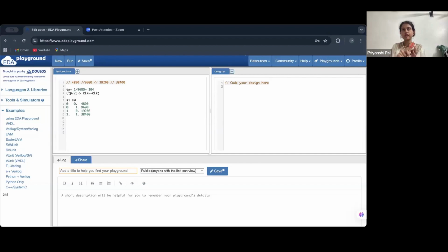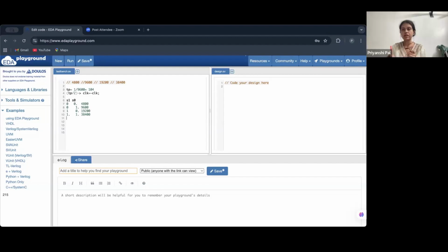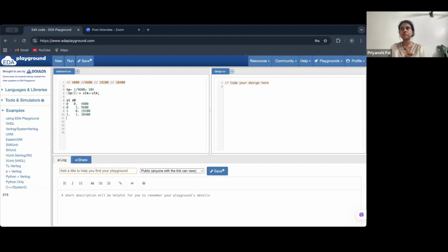The line for data transmission from master to slave is known as MOSI, and for data transmission from slave to master is known as MISO. So what is the role of the chip select in SPI? Chip select basically tells us which slave the master wants to communicate with.